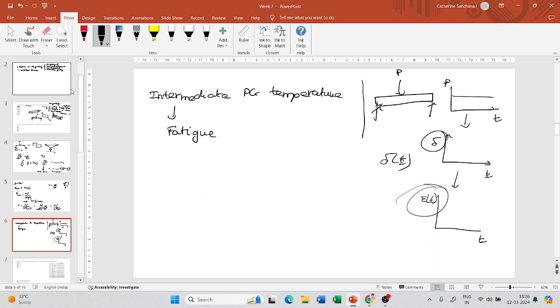Now you are going to test the bitumen in a DSR, dynamic shear rheometer. The dimensions of the sample we saw are 8 mm diameter and 2 mm height. You are going to subject the sample to some intermediate temperatures and measure the value of G star into sine delta.